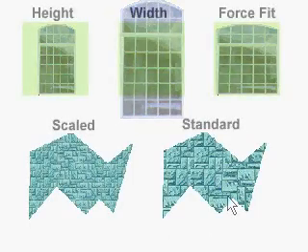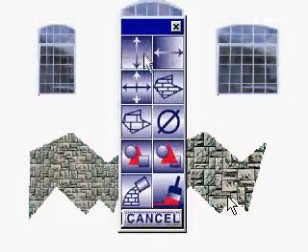The tape measure tool is used to define the scale of the image in your photo. Standard. The scale of the image library pattern is not changed. Use Freeform Standard for lawns and other non-building materials. You can change the autoscale setting in any area by right-clicking and then selecting a different autoscale setting.